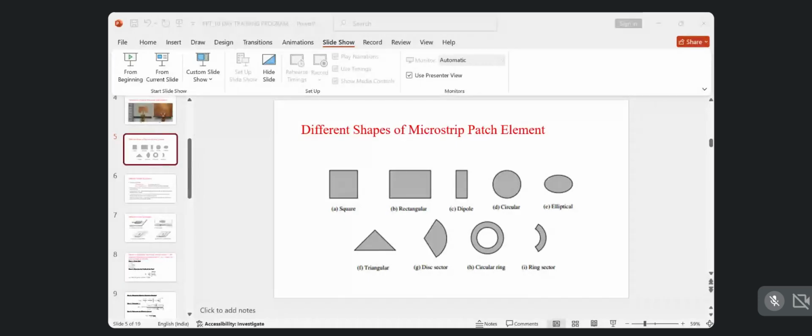You can just see this image. In proximity coupling feed, we have used two dielectric materials, epsilon R1 and epsilon R2. That is, you have two dielectric constants, and we have a patch as a radiating element. So your two dielectric materials or two substrates are stacked here. This technique is also used to enhance the bandwidth. The feed line is placed in between the patch and the ground plane, separated by two dielectric media.